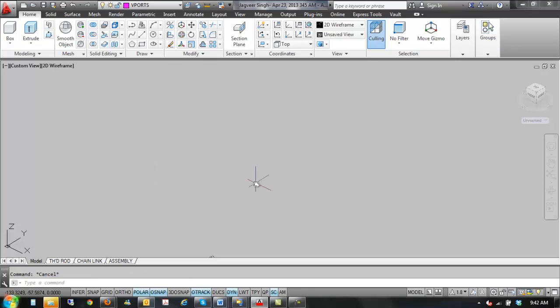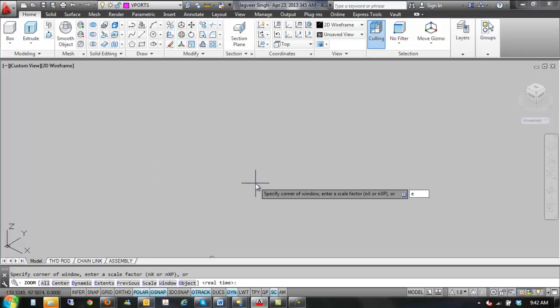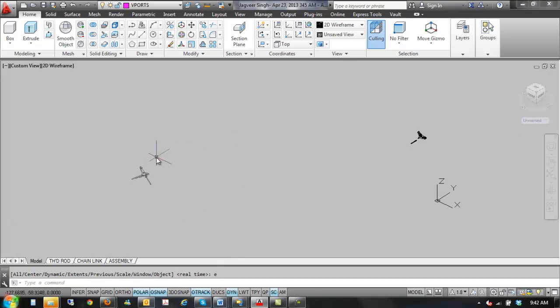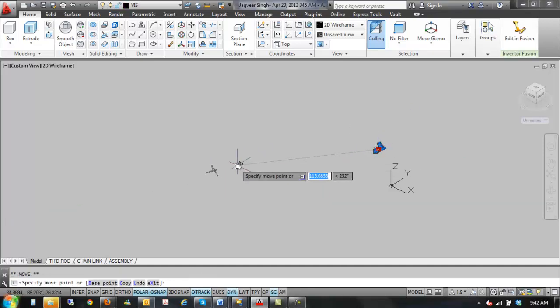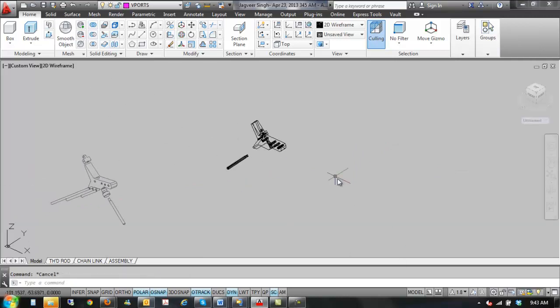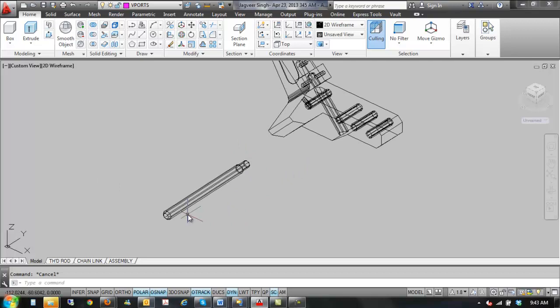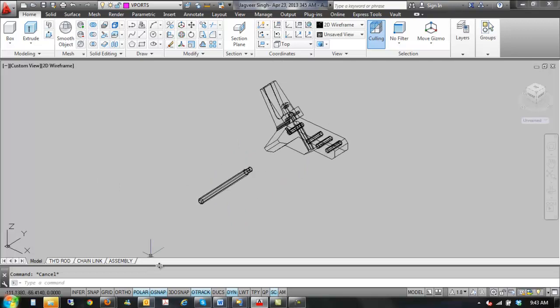Now, if I do a zoom extents, Z, enter, E, enter, I still got something over here. Now, this is the two-dimensional geometry. So I'm just going to leave that. Don't have to worry about that. But I could take this geometry and move it all a lot closer. But somewhere along the way we lost the rods, eh? So we can bring the rods back in. I don't know why they got deleted, because they should have been a 3D solid as well, or on the viz layer. They could have been on some other layer, but leave that for now.